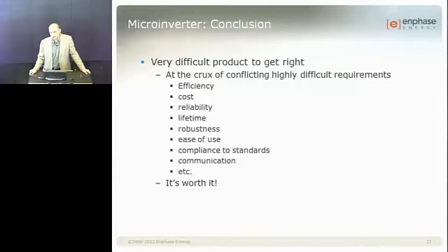The issue is that the module vendors warranty a product for 25 years, and it's really misleading, because what they warranty is the power production. All PV modules degrade over time, right? And what they warranty is that the degradation should be no more than whatever, 10% depending on the vendor, over 25 years.